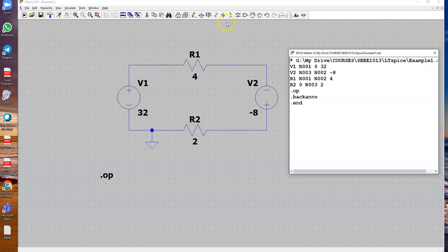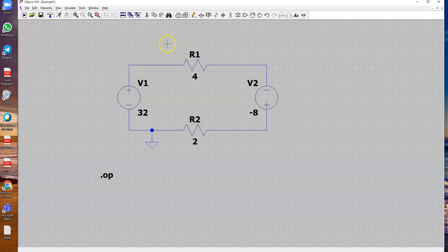All right, so to do that, you have to close this first. Okay, you move your cursor to the point where you want to name the node, right click it and then label the net here. Just call it A and then place it on the node here. This is the second node that we want to name. Just place A first and then we will rename that later. Right, and then we have C. So A, B, C, press escape to end that.